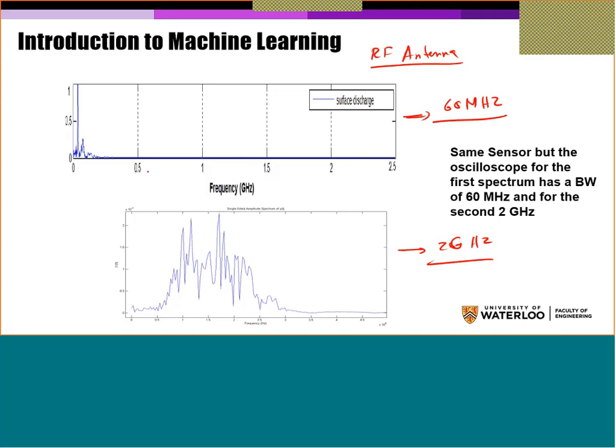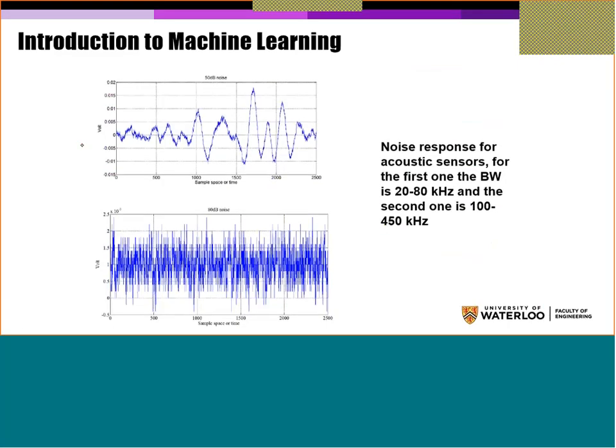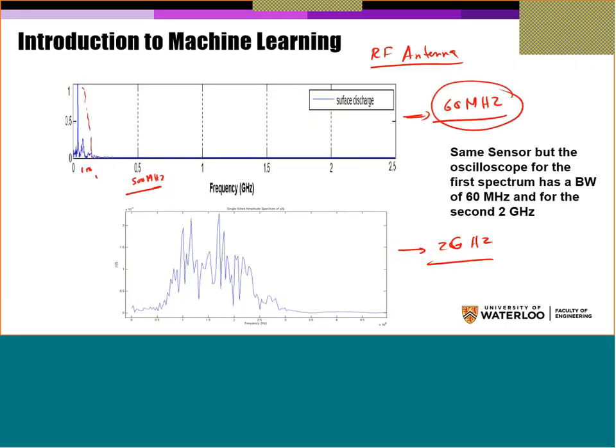So when you look here at this range, this is 60 megahertz. This now becomes like 500 megahertz, 0.5 gigahertz. So you see here the signal is around 100 to 200 megahertz. There is something here, but then nothing at all. Why? Because the measurement system that I have has this limited bandwidth, so I can only see things within it.